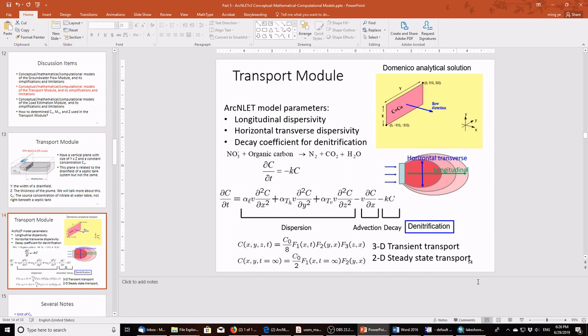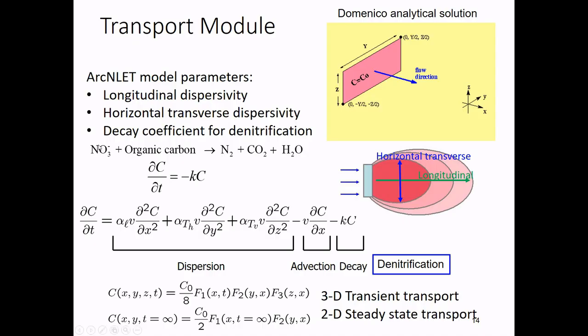We have used this word very often in the past, but essentially what it does is, let's say, you have nitrate, you have organic carbon, you have bacteria, and they use them to produce energy, just like people use meat to get energy, and the bacteria use nitrate to get energy. And then nitrate becomes nitrogen gas, organic carbon becomes carbon dioxide. You have water generated, right?